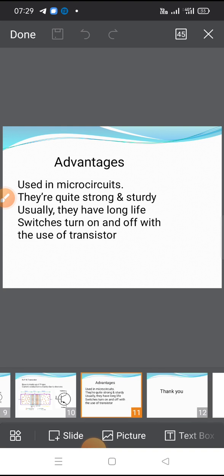The transistor can be used as a switch. The advantages which transistor switches offer over mechanical switches are that there are no moving or wearing parts. They are easily activated from various electrical inputs, and associated problems such as contact bounce and arcing are essentially eliminated.